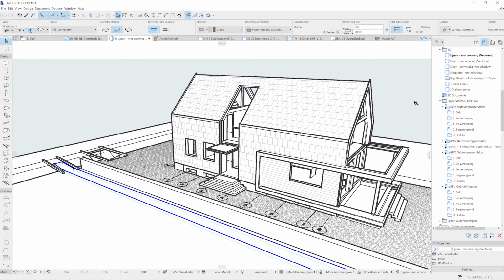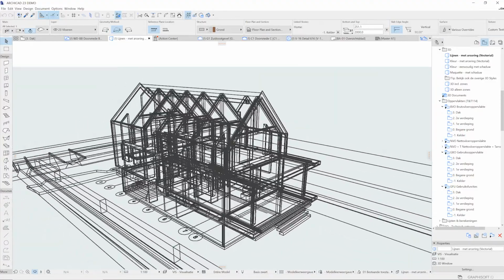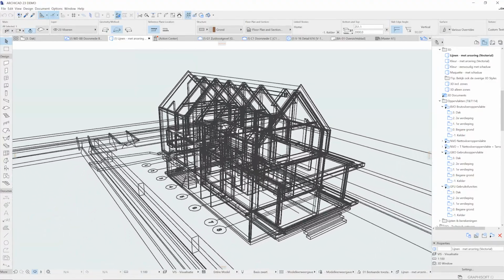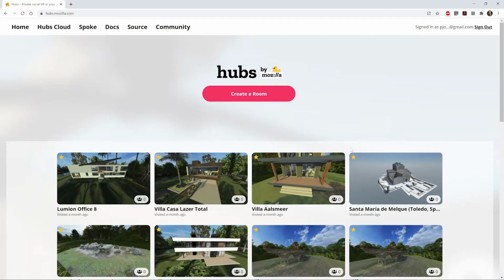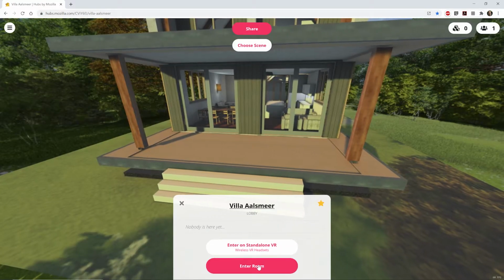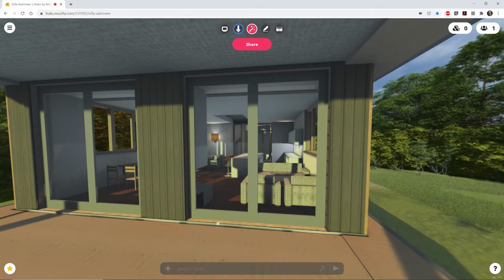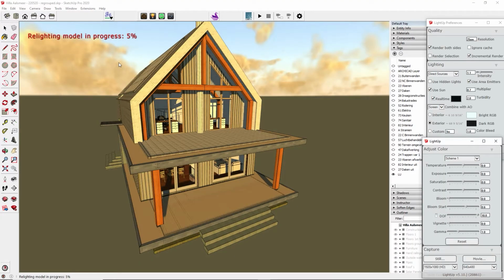To work with larger 3D models, like the ones created using BIM software such as Revit and ArchiCAD, we'll need a different tool to bring them into VR, as Sketchfab's VR performance is too slow for larger models. In this tutorial, we will introduce another free web-based VR system called Mozilla Hubs, which can better process larger models. We will also show you some light mapping techniques that are needed for these larger and more complex 3D CAD models.